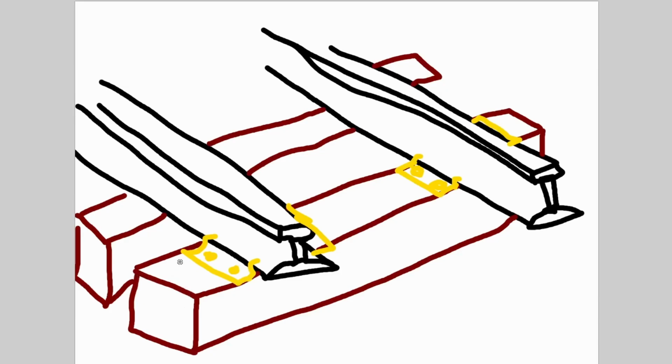So that's why the ties are treated with creosote. There's other treatments out there as well, and different things have been tried over the years, but that's pretty much the most common thing. There's another considerably important piece of tech that goes into railroad track that also seems to get lost in many cases, and that is the rail anchor. There are many different varieties of this, but anchors are an incredibly important way to help keep rail in place and also prevent kinks due to temperature.